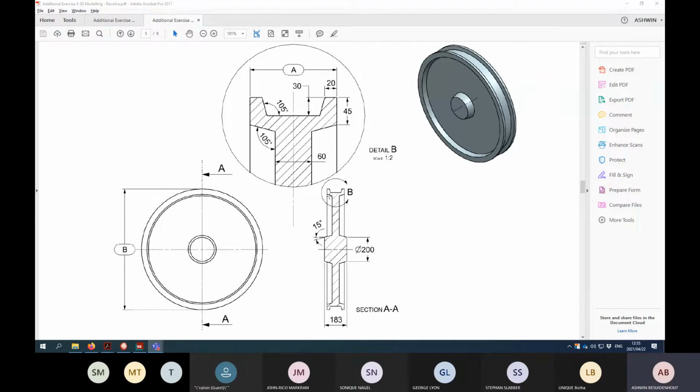So when you revolve, it will automatically pick up that that's an outer edge, and then it will complete this line as well, or have these views as well. Okay, so that's very important. One thing about this specific sketch again is we are looking at working with symmetry, and I will handle it as such. So I will only draw one half of it. When you work with revolves, you only draw one half of it.